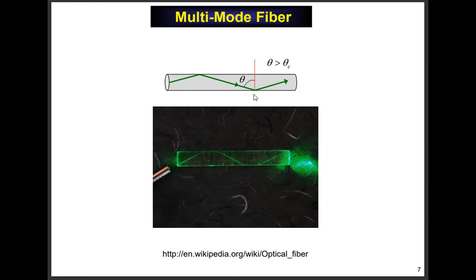And it says that the fields outside in the air region are decaying exponentially, but at optical frequencies, that's very darn quick. There'd be a tiny layer in the air region where you could measure some fields, but they're decaying exponentially fast. That layer where you can observe those fields might be just microns thick. So it's not going to work, and that's one of the reasons why you have that buffer layer, right? The wave has time to totally attenuate before it reaches the outside of the cable.